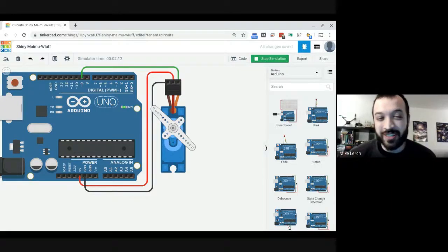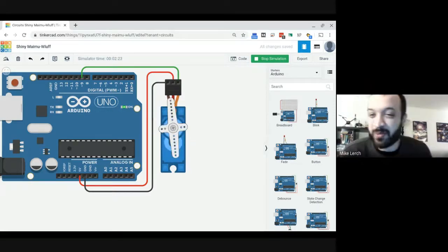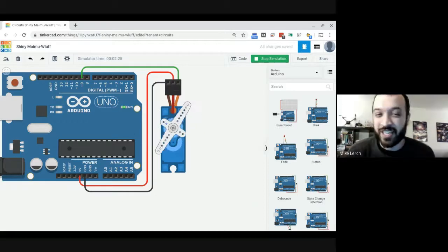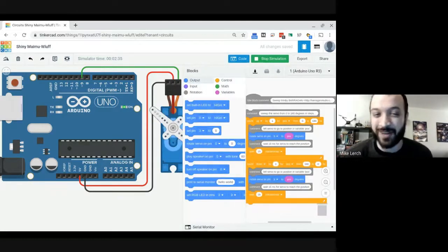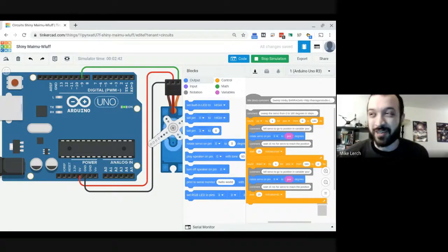I totally agree with you on that idea of controlling motors using some sort of switch, because the Arduino can't really support anything more than a half amp without resetting its own circuitry. So trying to power a motor that draws a lot of current and amperage will just cause the Arduino to reset itself. So what we have to do to get around that is have the Arduino and the motors and servos controlled by 2 different power sources.